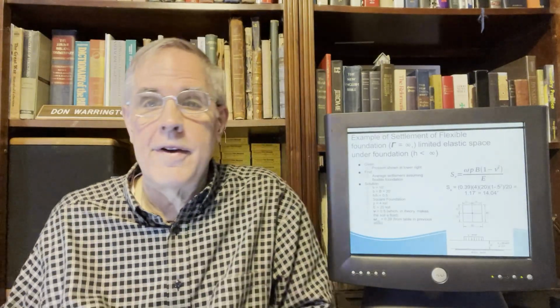It sits on a 10-foot thick, very soft soil. I mean, if you're talking about an elastic modulus of, in this case, 20 KSF, you're looking at some seriously soft soils. And nu is equal to 0.5.